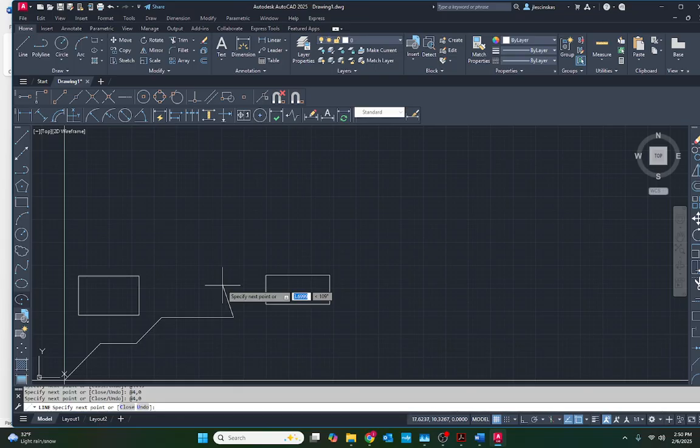This way you get used to it, and when you come to the point where you actually require the @ symbol, you won't end up making an error. So it's really not a big deal. We just type the @ symbol. So again, let's do 0, 4 this time. So now we're going to go 0 in the X direction and 4 in the Y direction. So now we move up by 4.